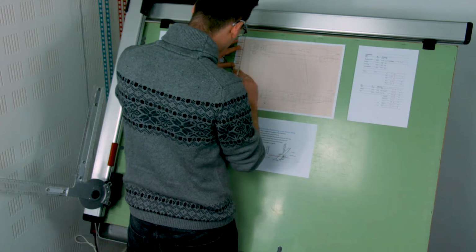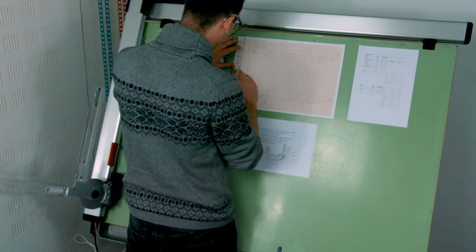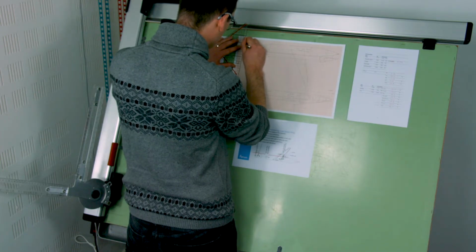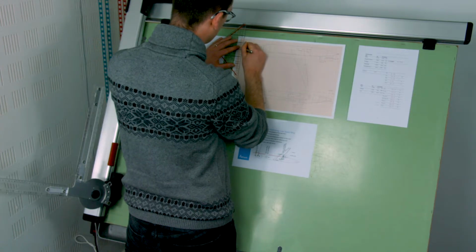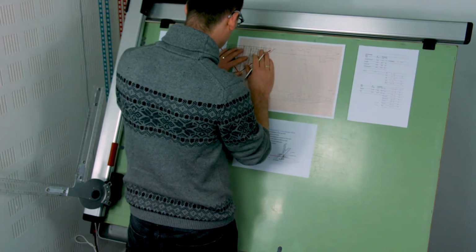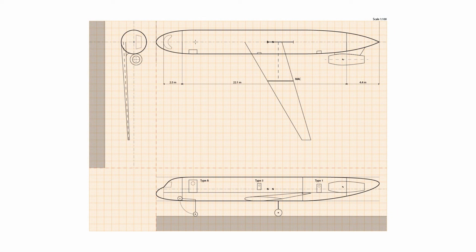So this is where the ground plane is. The main gear had a diameter of 1 meter, putting the ground plane 50 centimeters below the main landing gear axle, and then I can draw the nose wheel in very notionally here, leaving some space for the strut.